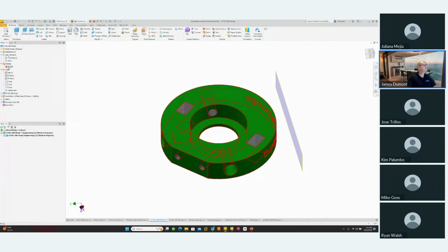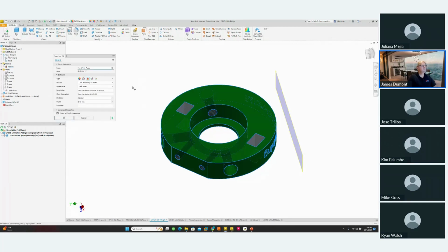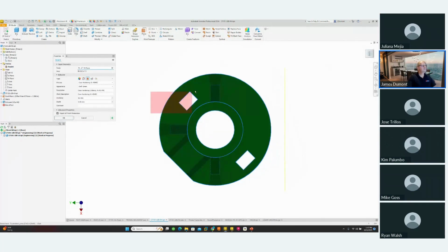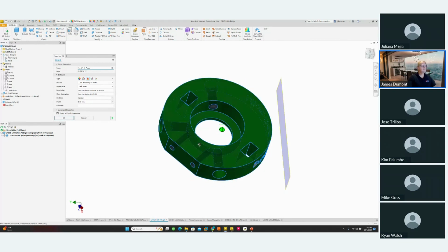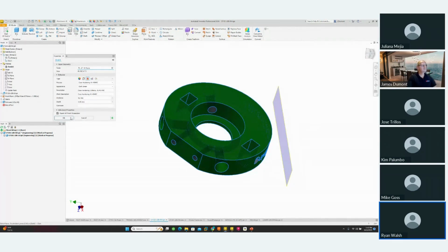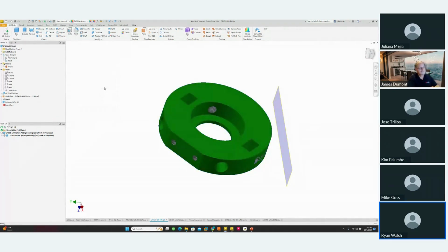So now if I enter my feature, you see those faces are missing. I still have 39, but if I were to do this, 43. Okay, now I'm at 40. So now I'm adding them. But it would have found those initially if you had done the faces after that work. Yeah, it's all about editing after the fact. We always want to make sure that it updates dynamically, and they miss that. So that's why selecting faces is not the best option.